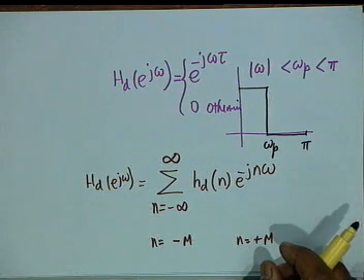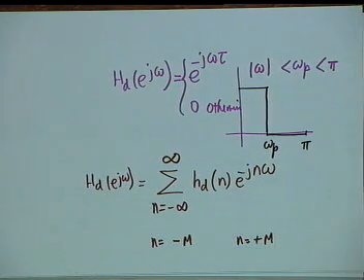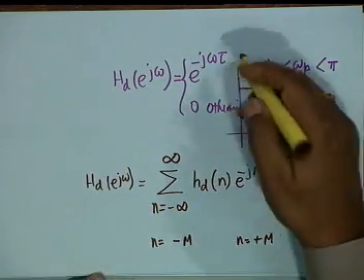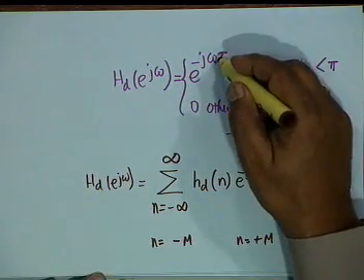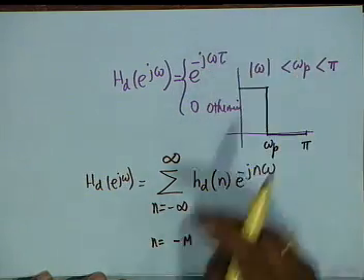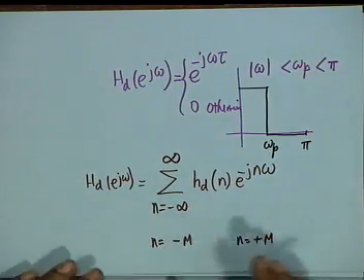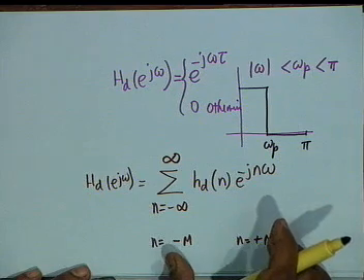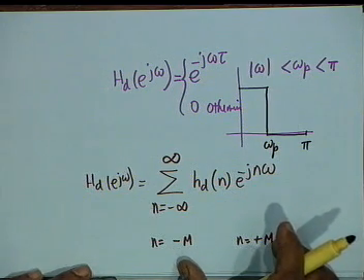Isn't that right? It will be a 0 phase filter because we have samples on the left and samples on the right. So, instead of e to the minus jω times a delay, it would have been 1. But in any case, we cannot realize a 0 phase filter. Why? Because the filter is non-causal.